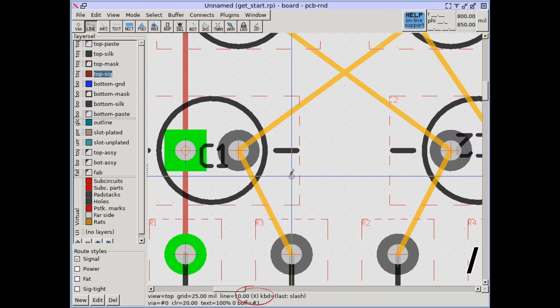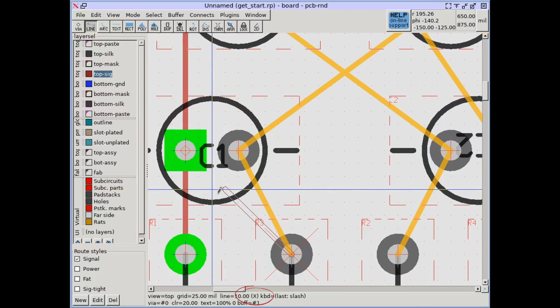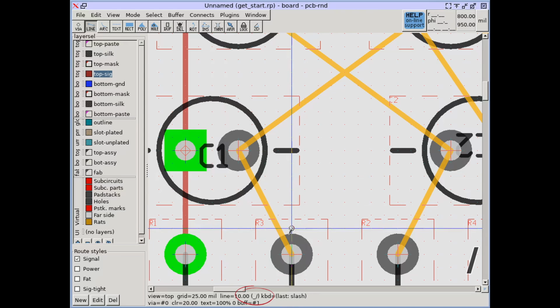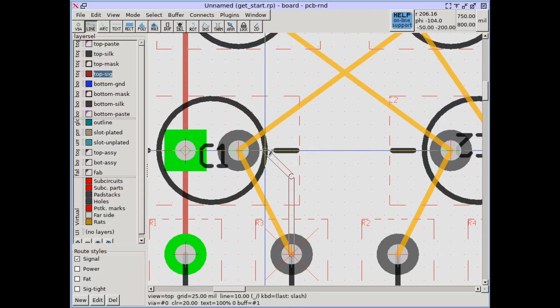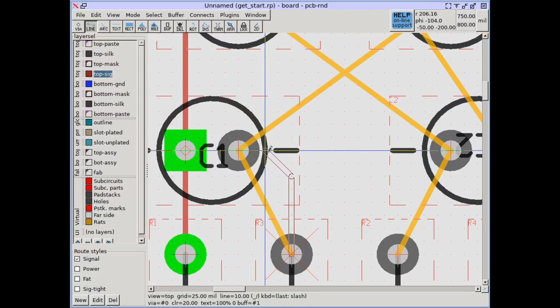Another slash key changes it to orthogonal mode, where only axis aligned lines are drawn. Return to the normal refraction mode by pressing slash again. It is possible to cycle through refraction options without leaving the line tool. Pressing the Shift key while moving the mouse temporarily overrides the current refraction.